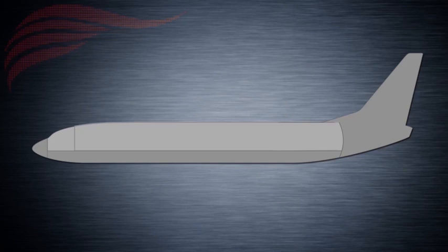The pressurization system uses bleed air that is cooled and filtered to provide the flight deck and passenger cabins with fresh air. For the most part, pressurization is achieved by sealing the cabin when the aircraft's altitude increases, thus avoiding contact with the external atmosphere. Air is, of course, modulated and disposed overboard the aircraft while fresh new air enters it, in order to maintain a constant cabin pressure.